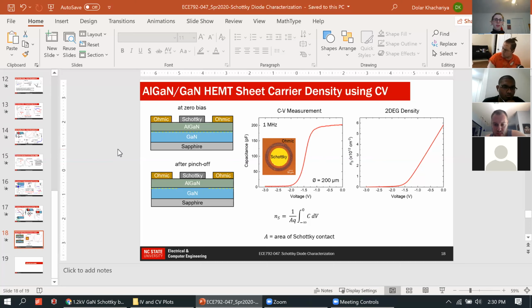One of them will be your drain current, which is what you are mostly going to be looking at to analyze the performance of the FET. And you're going to use that to find out the threshold voltage and all those other nice things that you care about for a transistor. But for the depletion mode HEMT, or the Schottky gated HEMT, you can look at the gate current relationship with gate voltage applied, and that's basically going to be a Schottky diode behavior.